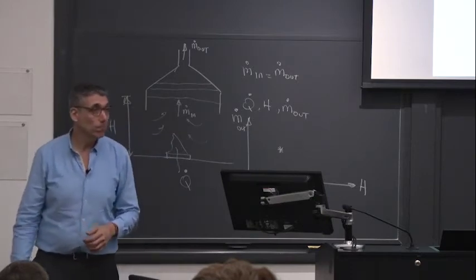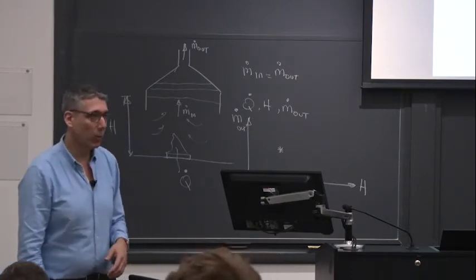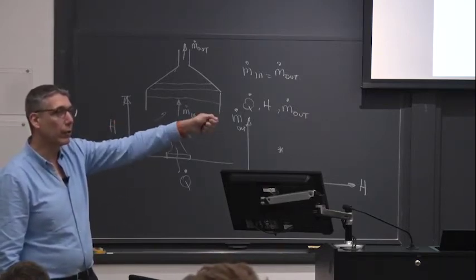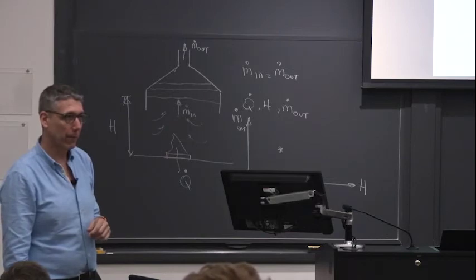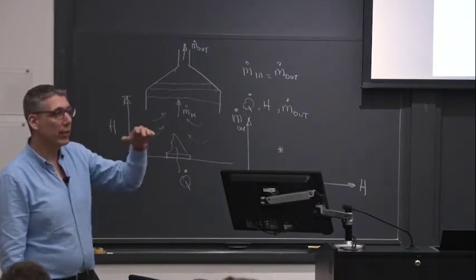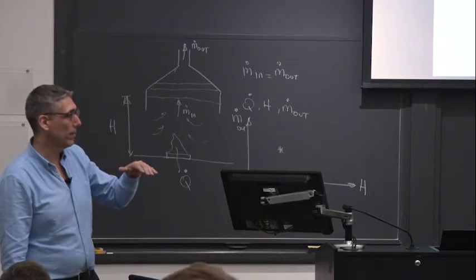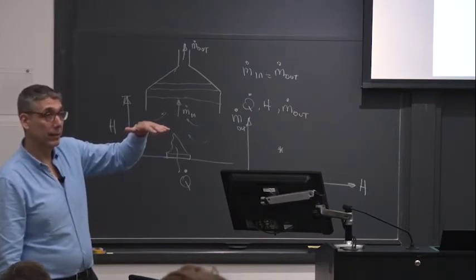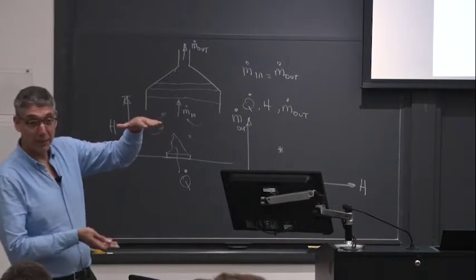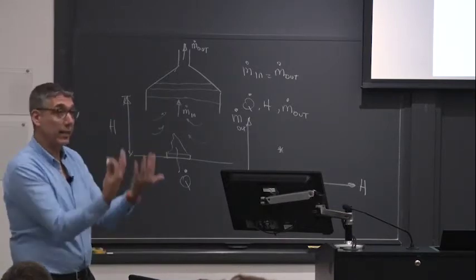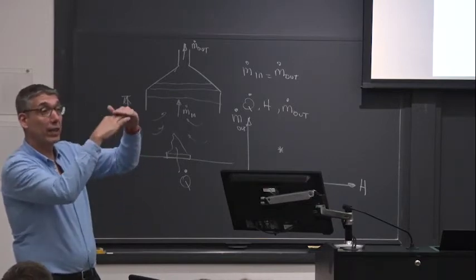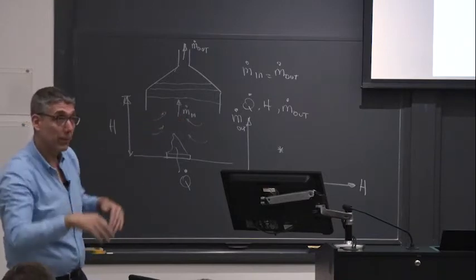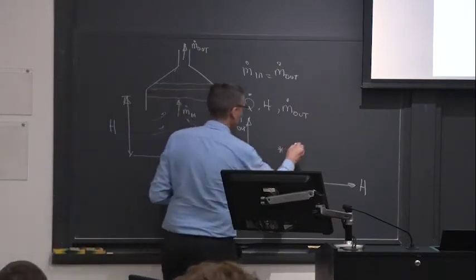Is that okay? So then next experiment, what am I going to do? Once I got it once, I'm going to tell the student and say, now increase the extraction. So the moment they increase the extraction, what is going to happen with the smoke layer? It's going to go up until it stops again, no? Because as it goes up, your M in increases, and therefore eventually they balance each other again, and then you get a new H. Is that okay? So then I get another point.